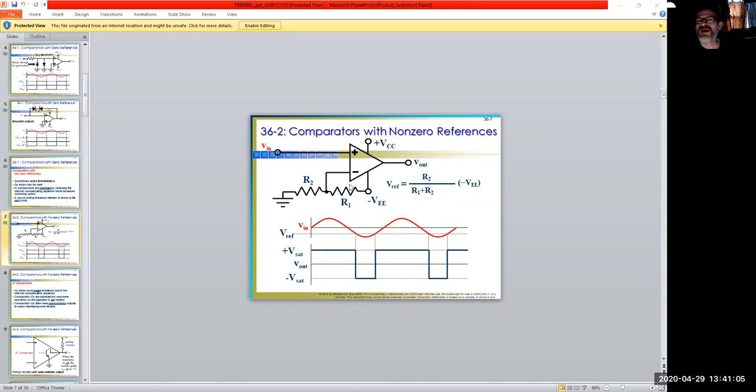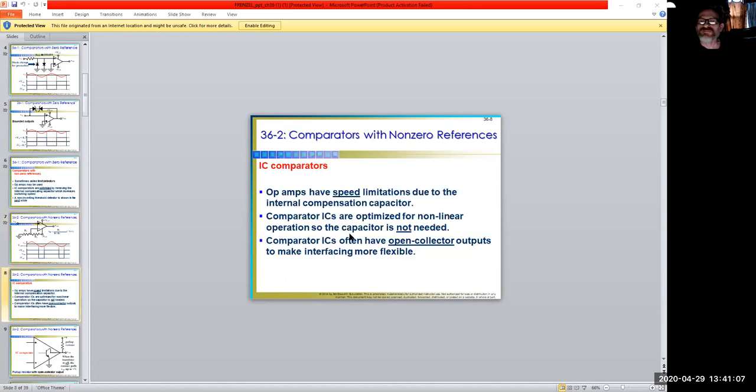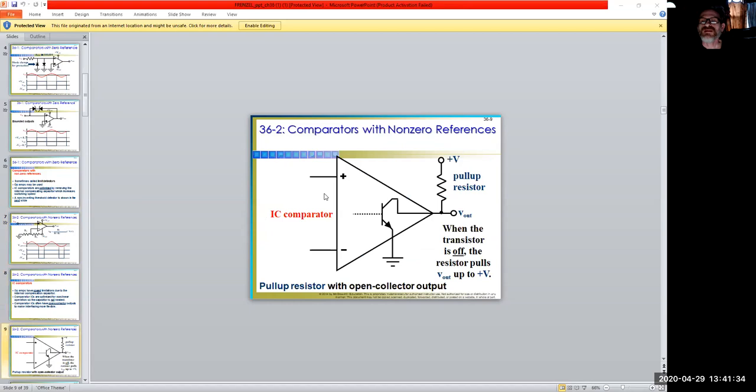And this is how the model changes. So as far as linearity, linear response, that kind of goes out the window. And that's a cool thing with comparators. And remember, the golden rules of the op-amp device itself don't change. It's just the way in which we use them, by taking away the feedback loop compared to having a feedback loop, and how the device responds to that.